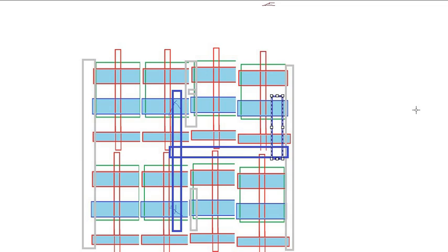So what I'm trying to convey here is the metal layers also have a lot of cut layers in between. Depending on whatever metal you want to cut, you need to use that type of coloring for that particular cut layer. So we generally have cut layers for lower levels, that is M0, M1, M2, and M3, right? You have cut layers for these. Now, depending on the technology, you have cut layers for all kinds of metal. Generally we don't have them for higher metals, since the width is much higher and that is not required as per the technology as well.